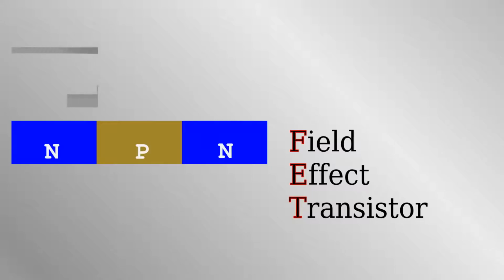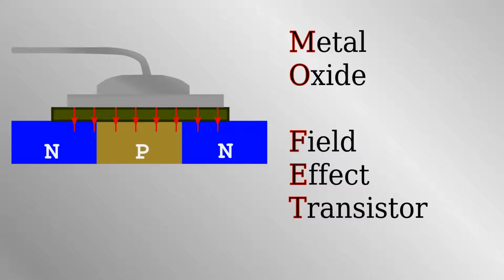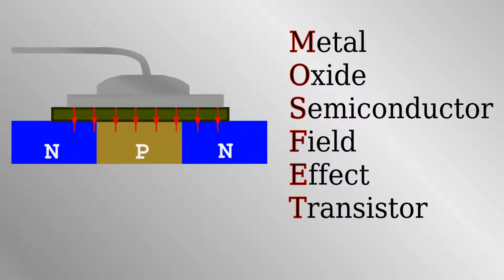Near the semiconductor stack, we have a conducting electrical terminal. When it's at high voltage, an electric field forms and the transistor conducts. But, to stop a short circuit, we need to add an insulating layer between them. The contact is metal, the insulator is silicon oxide, and finally we have the doped semiconductor, hence the term MOSFET. For a computer, we need millions of interconnected CMOS pairs, and they must be small and close together so that electrical signals can travel between them quickly.